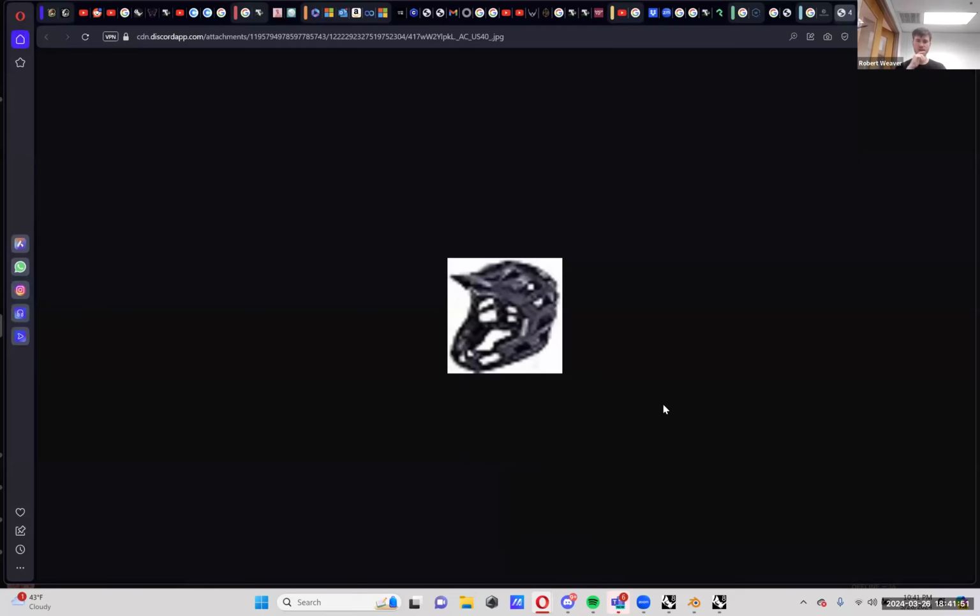For this one, you could definitely start with just laying out the surfaces. Maybe do a surface for the chin, a surface for the side of the head, one for the top, and then you could map patterns on that, very controlled. And using attractor points, you could do different grid pattern shapes or something like that. You could do directional holes as well. If you're thinking about that, they don't just have to be normal to the surface. You could add in any vector to have the holes go at different angles.